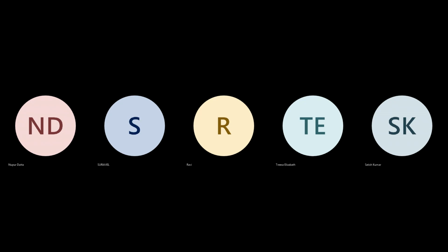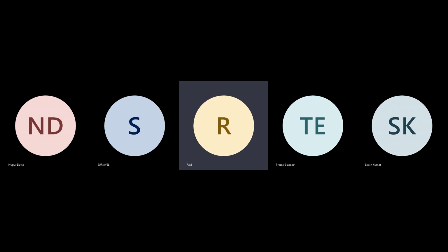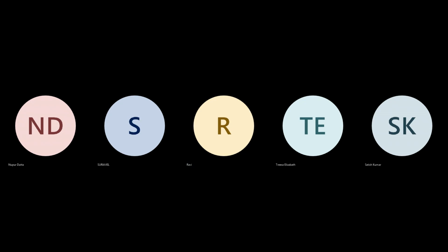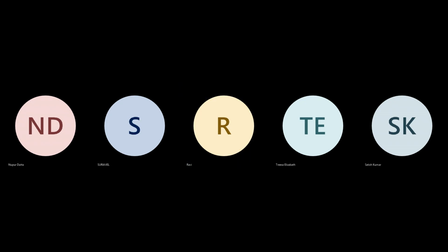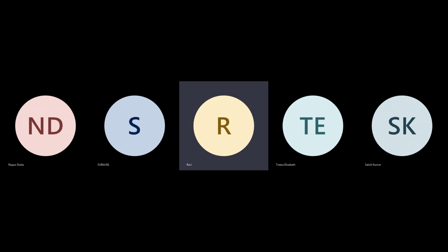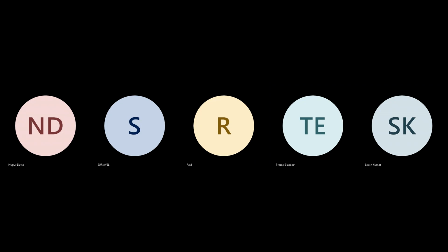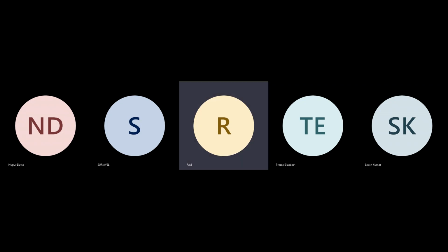Placement. Yes, so define as many things, but simplify. Keep it mission critical. You understand? Okay, whenever you are running placement for the initial trials, don't try to focus on your IO type name. Keep IO's loose. First, allow your internal timing, whether they are meeting or not.